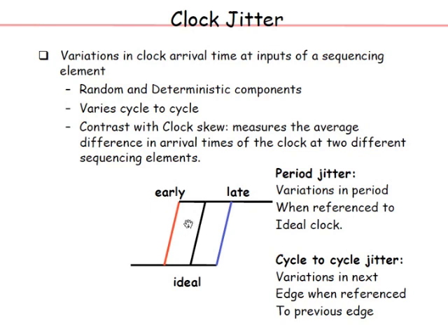That is why, when you observe it in the scope, you will see that the edges keep on fluctuating. On average, it will be 1000, so there is no drift. Drift means the frequency is a little bit off. It's not exactly 1 gigahertz, but 1 gigahertz plus 0.1 or something. Then the frequency is a little different, so it will slowly walk off. We are not talking about that. The frequency is controlled, but you will still find this randomness in the period, called cycle to cycle jitter.